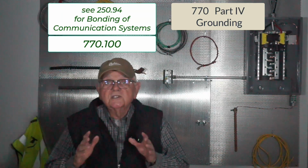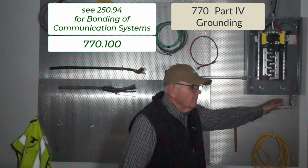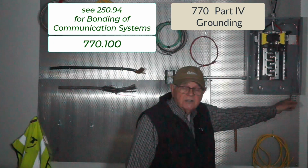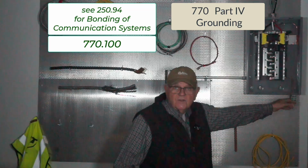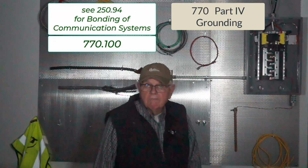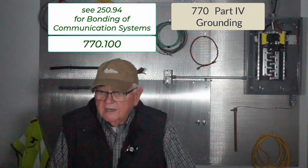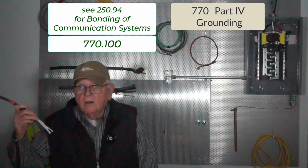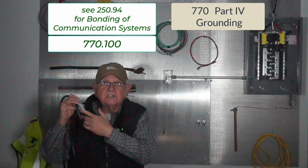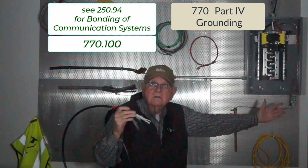Now, big question is, what if I don't have one? 250.94 says I have to have an intersystem bonding termination here. But there's an exception in 250.94 that says, no, in existing dwellings you don't need one. Well, because we don't have to go back and modify it, do we? Oh, well, great then. Now I install my cable. It's got the corrugated metal sheath. I need to run an intersystem bonding termination, but where do I connect it?